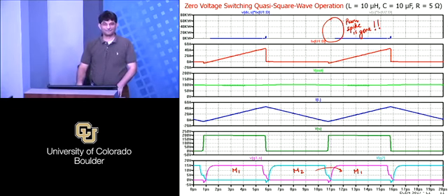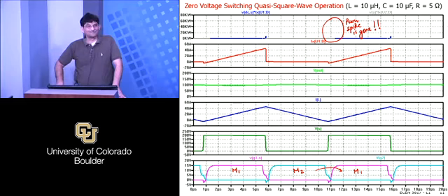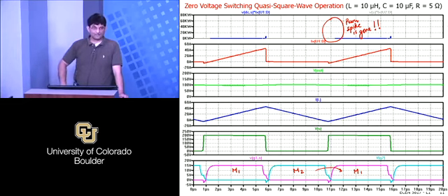What happened? Ooh, magic. I just changed the inductor value from 100 microhenry to 10 microhenry, and you have no power spike. That was the problem, that was the big loss. That was the diode reverse recovery. If we add capacitors, there's capacitor discharge and charge loss as well. All of that's just gone.